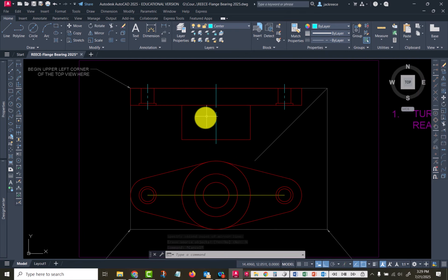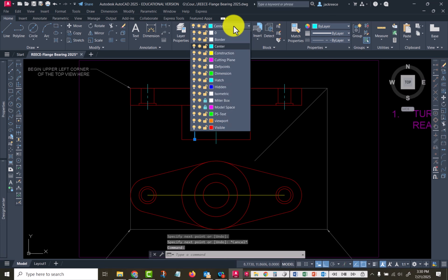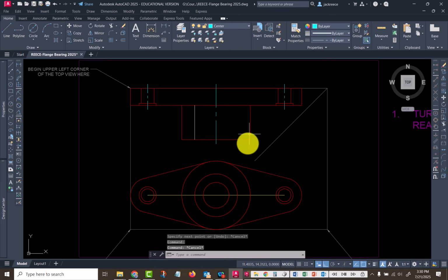Now the countersink here in the middle. So let's draw the, yeah, we'll go ahead and project both of those lines up. So let's, oh, the line didn't take. Okay, so let's project from here. And I'm gonna put these on a construction layer, make them a little bit easier for you to see what we're working through here. Okay, and then the edge here, and that will go all the way through.